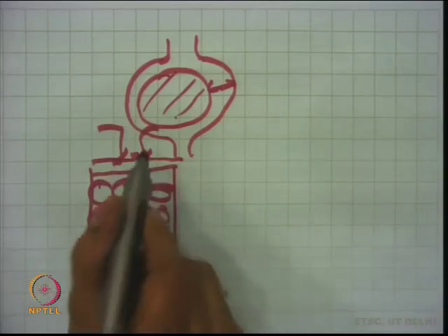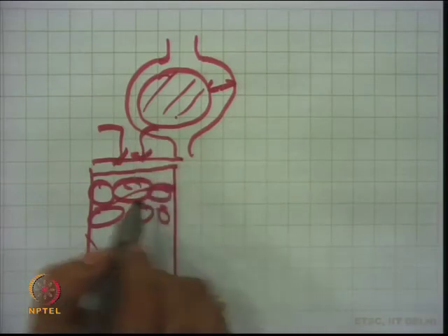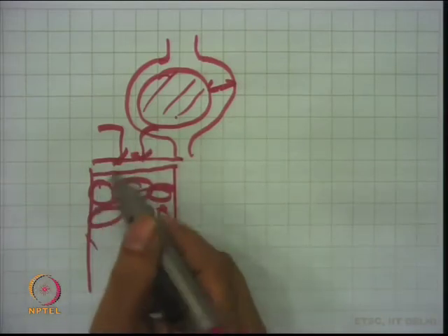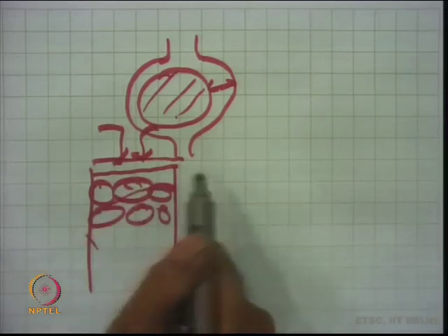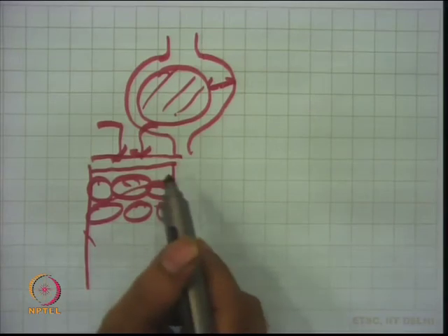So, distributor design in the trickle bed reactor or any multi-phase reactor is very important, right. Channeling is to be avoided, because of dead zones and channeling, they will affect the performance of the reactor or decrease the conversion inside the reactor.